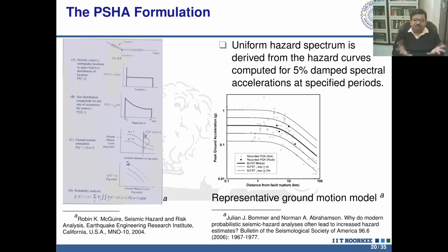Now, we know from the basic physics of the problem that every large earthquake is preceded by a few foreshocks, and aftershocks continue after a long time. So these are not really independent events. This is what we call a cluster, when a large earthquake will always occur in a cluster. So in order to make this data suitable for Poisson process modeling, we use what we call a declustering process. Now it is not an exact science because we don't know how the aftershocks are to be distinguished from the main shock.